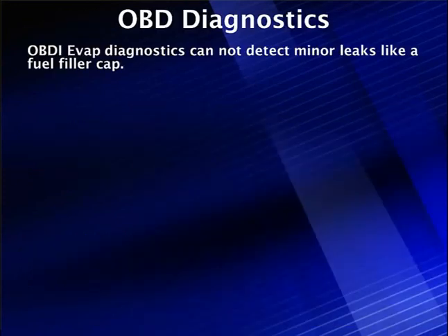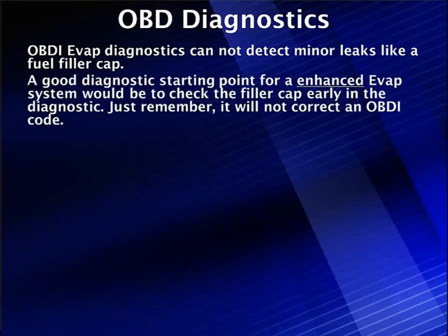OBD2 diagnostics could not detect leaks like a filler cap. So if you're working on one, don't think that. If you have an enhanced system, a good diagnostic starting point would be to check the filler cap early in the diagnostics. Just remember, it will not correct the old OBD2 problems.